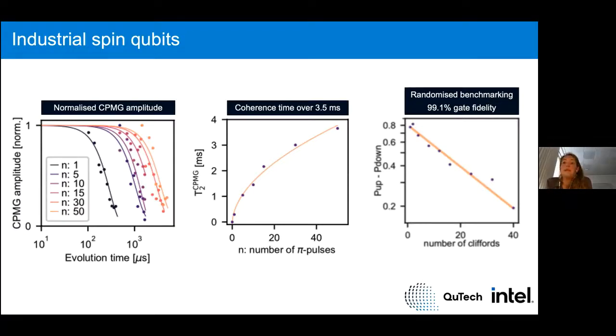And therefore, we expect that if we can solve this issue with the heating of the sample and maybe a little less spurious dots in the vicinity, we can actually get higher gate fidelities, because indeed there are quantum dot samples in our community that have similar coherence times, but way higher gate fidelities, such as, as I said, the 3 nines. So I think it's mainly a problem of calibration and heating.